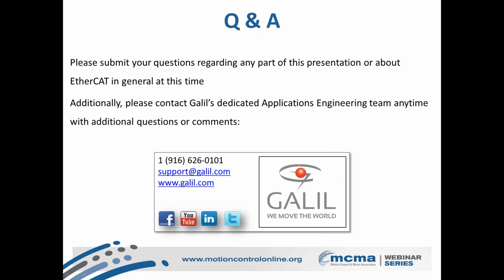And if they did know they were supposed to get something, now they have to signal back to the master and say, hey, I didn't get that data. The master has to resend it. At that point, the benefits of EtherCAT, the coordination and determinism, have been lost, because now you don't know when that data is coming back and forth, and literally your motors are sitting there waiting for instruction while your wireless signal pings around the building.